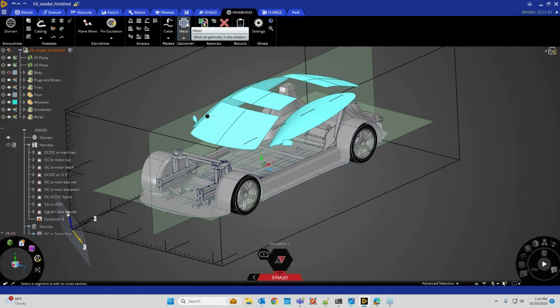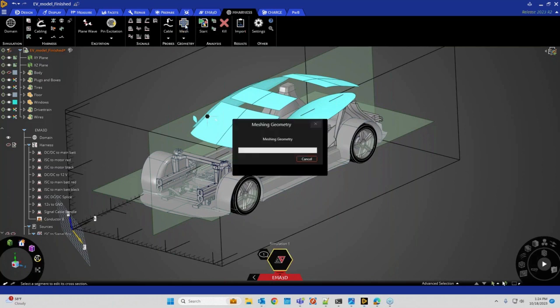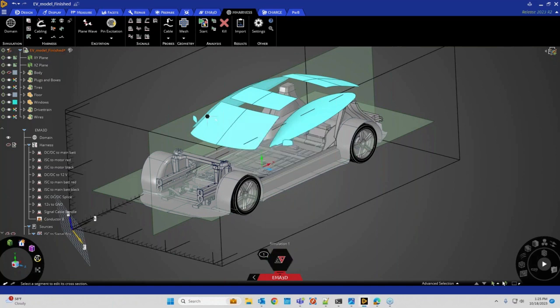And then what you do is you would just click mesh, which I'm going to do live here. It should take about 20 seconds, I think. But as John mentioned, voxel style mesh is very forgiving. It's very fast. It doesn't take a lot of CAD cleanup to get it going. So now it's just going to show me my mesh here. It has finished meshing.